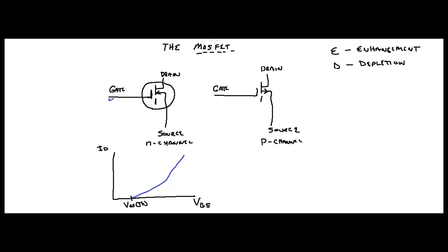I'm not going to go into the P channel, but basically, well, why don't I just do this for the heck of it, right? Your P channel is going to be, here's your VGS, right? And here's your VGS threshold. By the way, it's negative, obviously, right? This is your ID. And then if we look at the chart, it's going to do this same thing, like that.